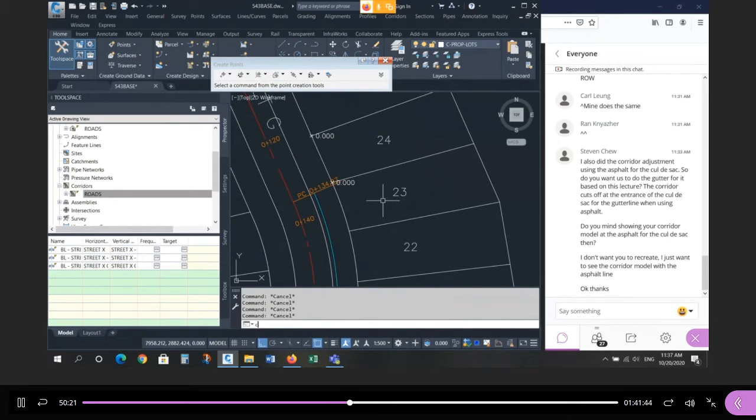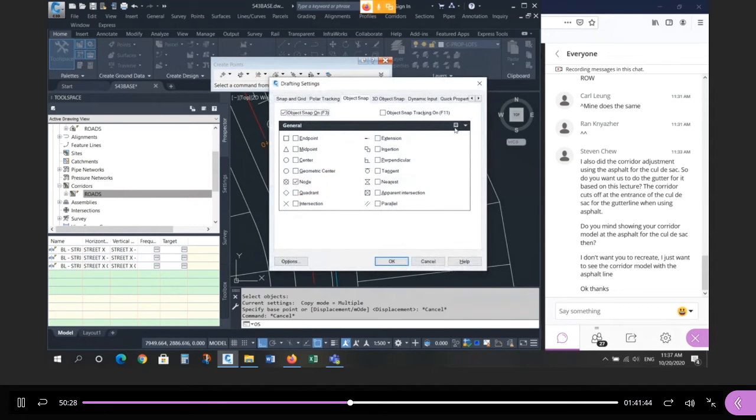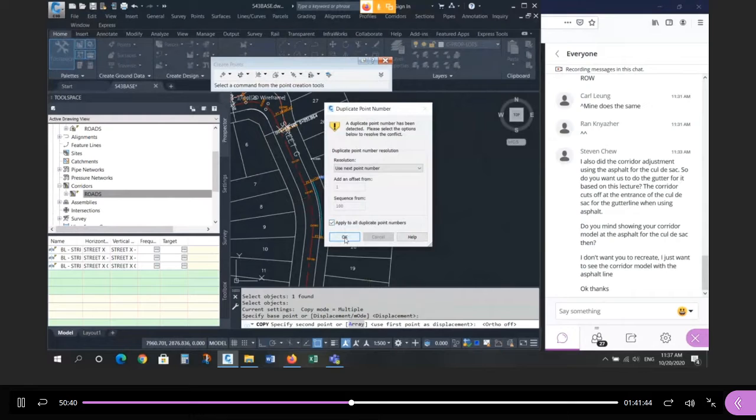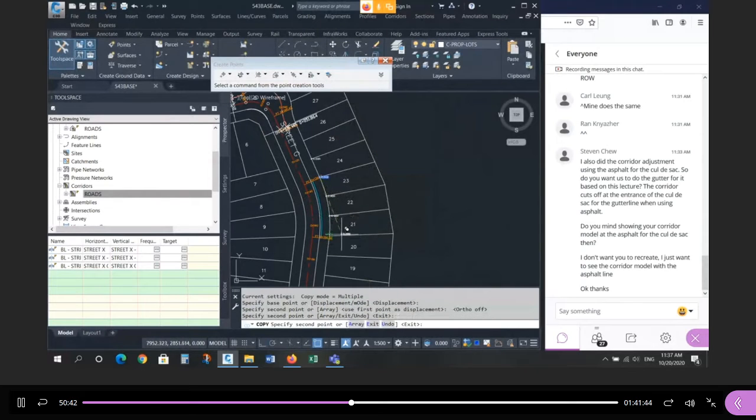Once you create one point, you can create a copy of it. So I'm going to grab this, and turn your O snaps to end point. Once you create one, you can create a copy, endpoint, and go to the endpoint, turn this on so that it knows how to sequence it. Number, endpoint, endpoint, endpoint, go all the way around all the front lot corners. That's on one layer in one group.